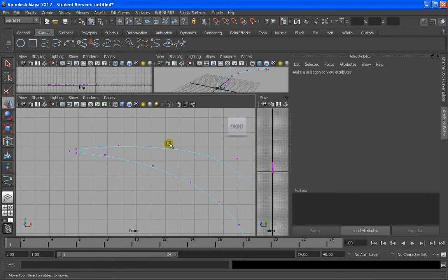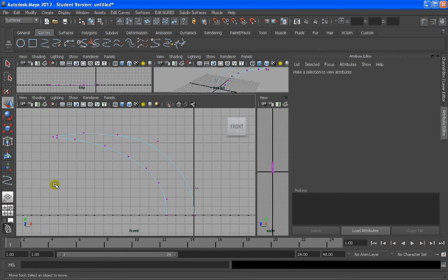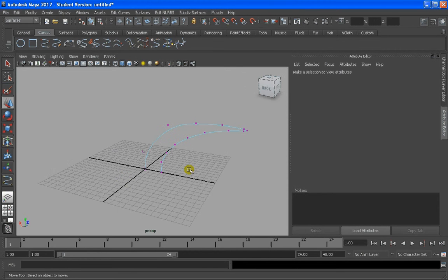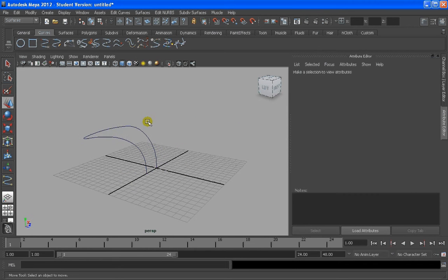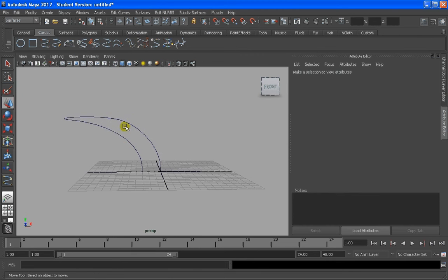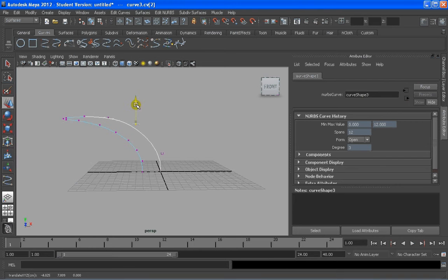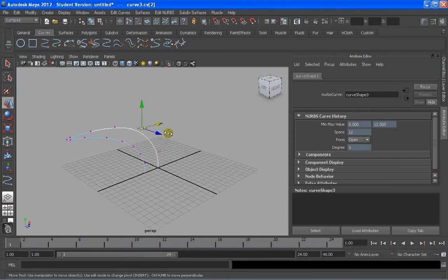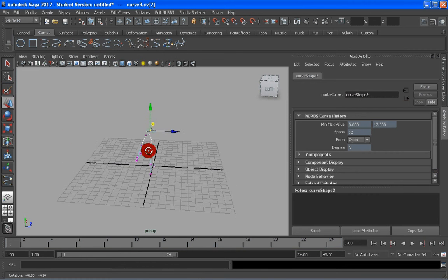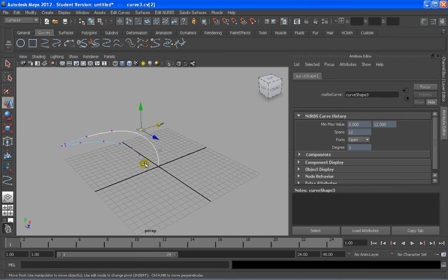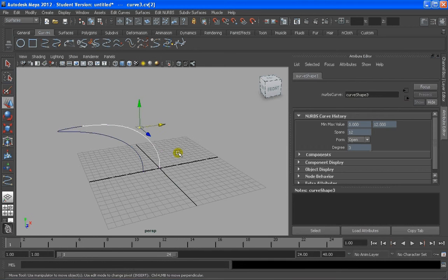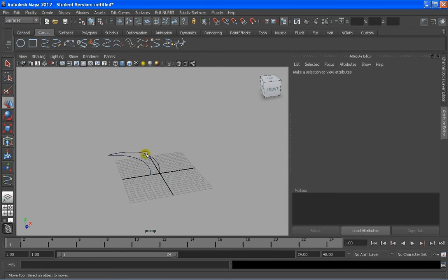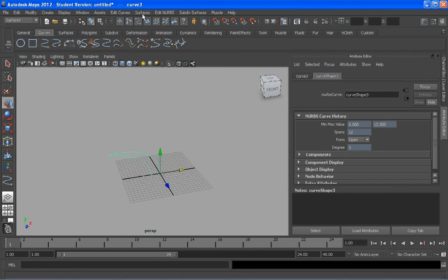I like it. Let's go to the perspective and see what we have here. Let me right click in object mode, and we have this type. I think this one's a little high, but let's go to control vertex and take this one lower down here. Remember, I'm doing it from perspective, so I have to be aware that it has to always be in this plane, because I'm going to do a revolve through this axis. So I'm going to object mode, and let's do a very simple revolve, selecting the profile and saying Surface, Revolve. There we go, and it does this.